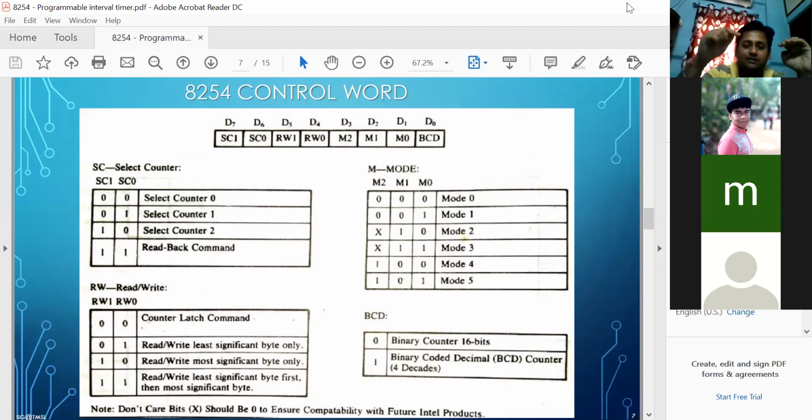Now, debouncing is to minimize the bouncing. You have to take the input only in a stable condition. If the signal is fluctuating, there is already noise, and you could take that noise as your input.